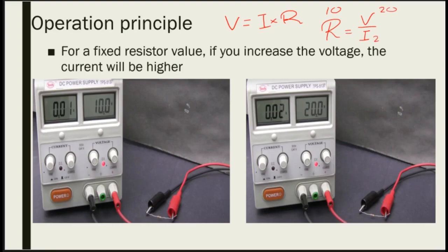All right. Let's say I increase this to 40. What would be my new current? 40 divided by what still gives you 10? 4, which makes sense, right? You upped your voltage, but you didn't do anything to the resistance. So you upped your current as well, right?